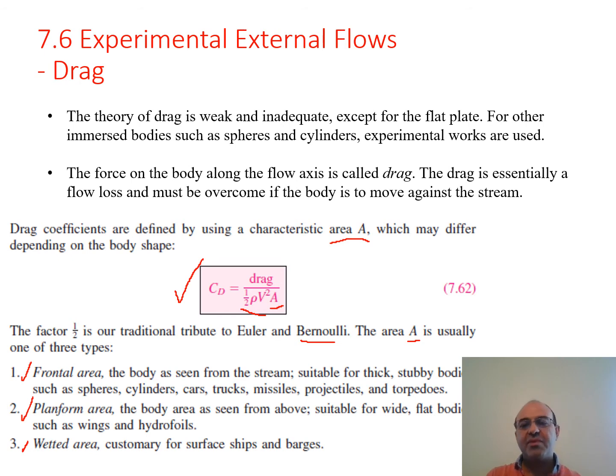So when we consider the drag forces, we need to be careful what kind of area is supposed to be used to calculate the drag force. From tables, for instance, you may read the drag coefficient CD, and then in order to find the drag force, you need to multiply it by these other parameters, including the area. And it has to be clarified what area you are going to use to find the drag force.